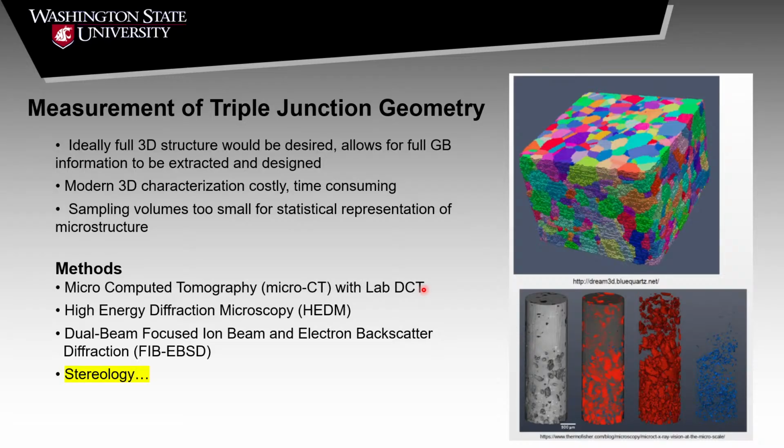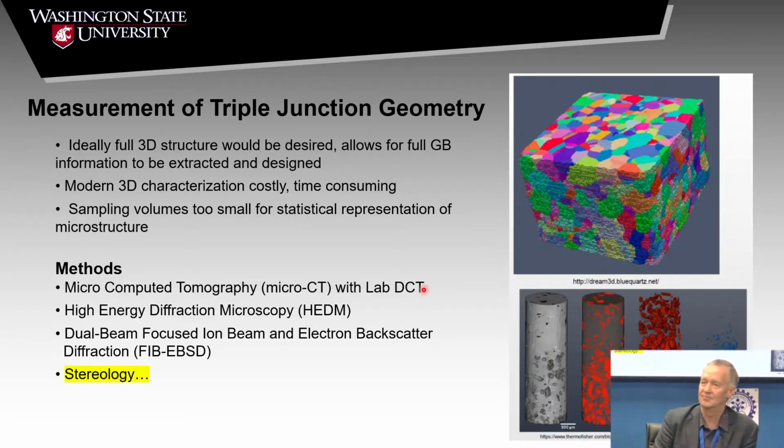There's something called U lines and I lines in triple junctions. And it's talking about the character of the boundaries that form those U lines or I lines. So you can categorize triple junctions saying this is a good triple junction or a bad triple junction. It has special features or it has not special features, right? U and I lines we call them. Okay? So there's a lot of work in these types of areas in triple junctions. But it's assuming a lot, and it's not understanding what the true space of the triple junction is.